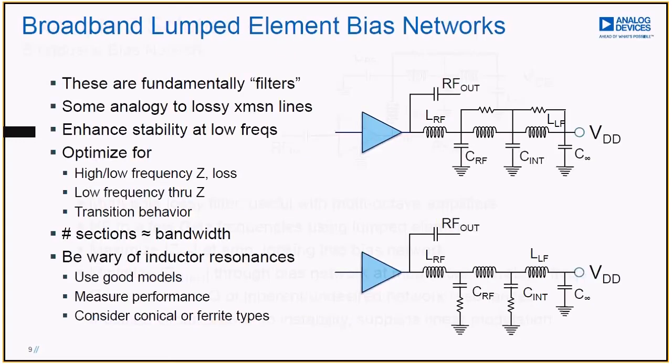There's a couple of implementations of this classic circuit. The top circuit, we have Rs in parallel with the inductors. In the bottom circuit, we put Rs on the capacitors. It's very similar. Either circuit will accomplish this. You'll see designers use both solutions, and be creative. You can mix and match this. But the general reality is just like in a filter, if you want a sharp transition between that rejection band and the pass band, you're going to need more sections.